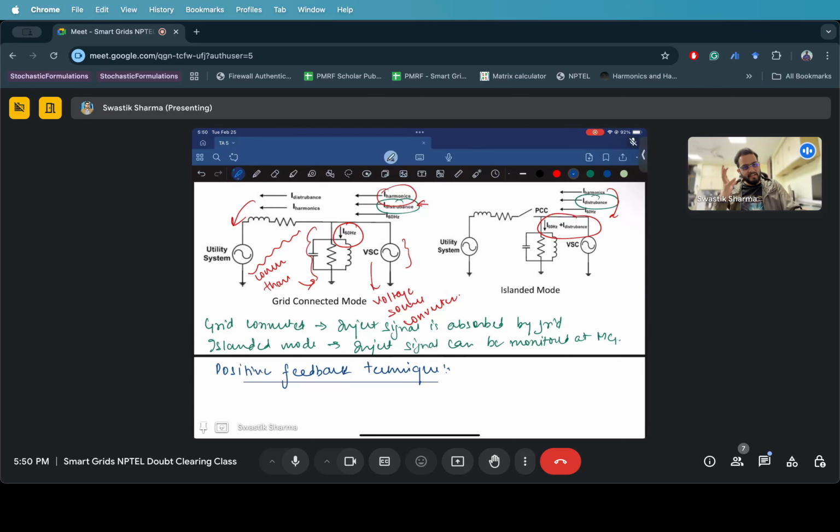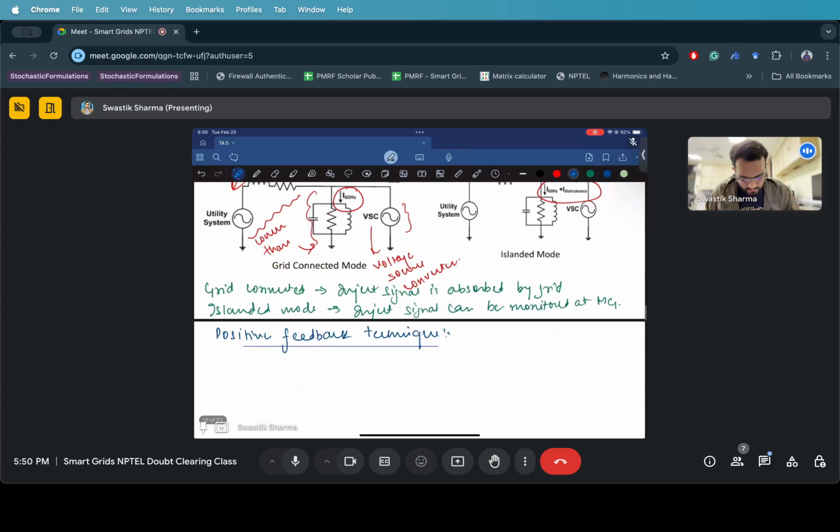So it's continuously tracking what the voltage is at PCC. Now let's say you change some electrical quantity in your inverter, for example the phase angle or some voltage, as an output of your inverter, just so that your DER now behaves in an unstable mode of operation, right?